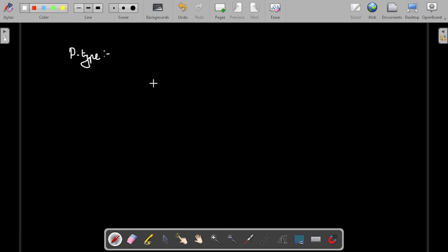the p-type. So in order to make the intrinsic semiconductor an extrinsic semiconductor of p-type, we need to dope with the trivalent atom. So the trivalent atom is our interest. The example for these trivalent atoms is majorly boron. In some cases we also use aluminium. So let's take a crystal lattice structure of silicon. Here we can use boron as the doping atom. So let's take some simple atom of interest.